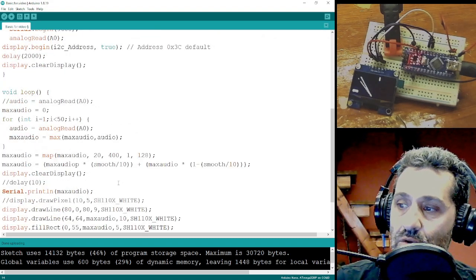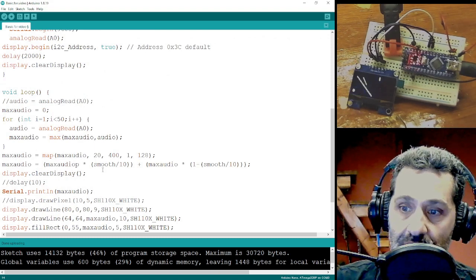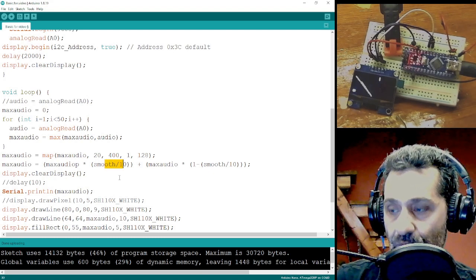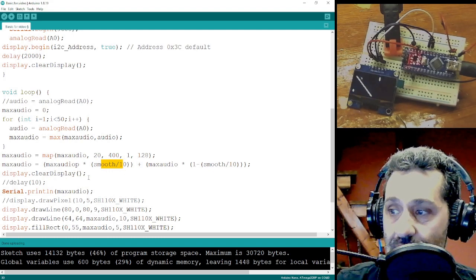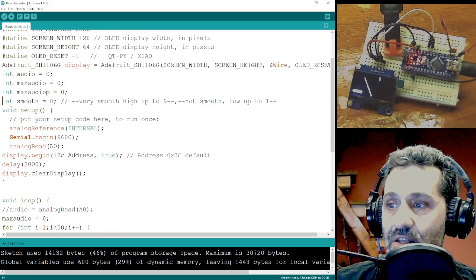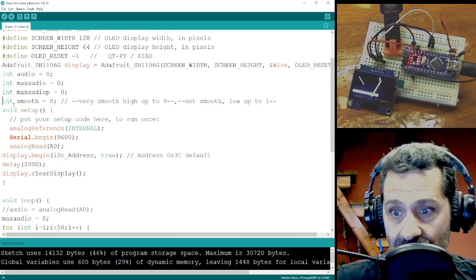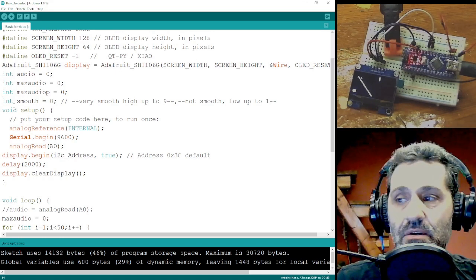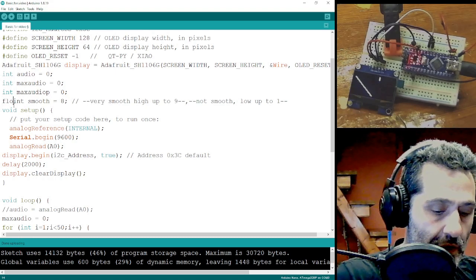But on the Arduino, when you make calculations with a variable declared as integer, the results are always only integer. So this, for example, although it should be 0.8, it will be rounded to 1. So if we declare this variable and we want calculations with this variable to result to not an integer but a value with decimals, this is called a float.